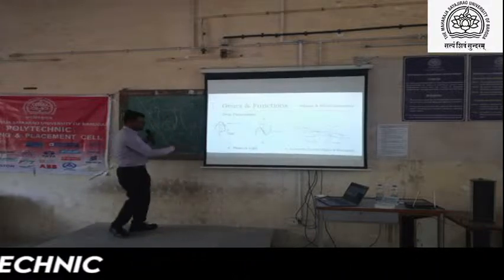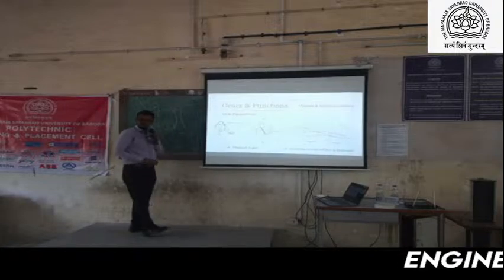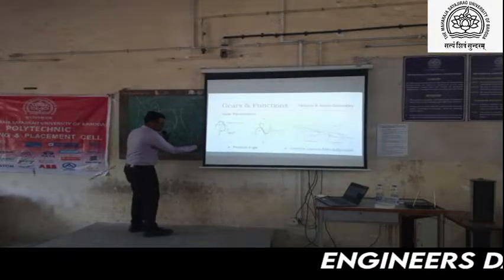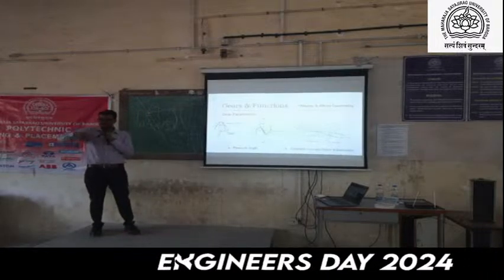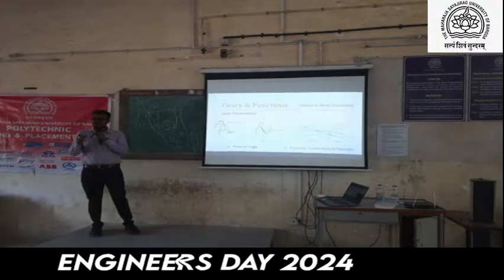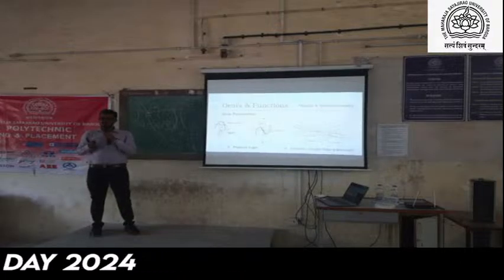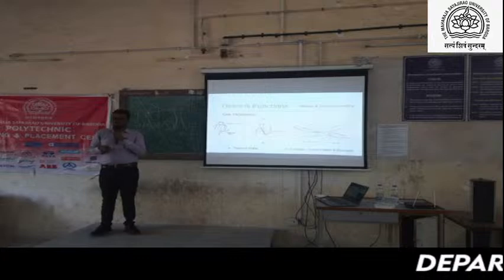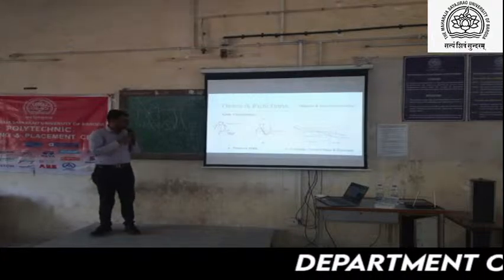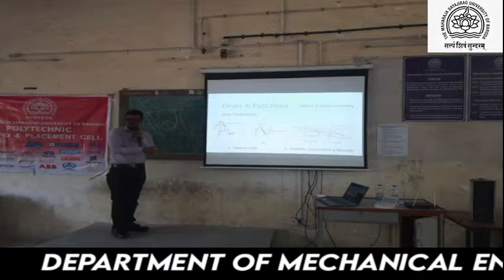Yes, no? Helical will have some angle like this. So this contact area, the entire flank contact, will be considered as the transverse contact ratio. Everyone can catch me now? If you have any doubts, just stop me there. So this is transverse contact.